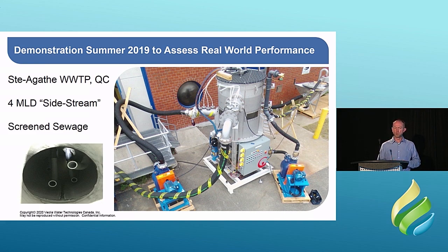Those are the sample tubes. And the bottom left photograph there is what those tubes are connected to. So those bendy pipes are picking up sample from various locations in that influent pipe. The whole idea being to get that representative sample. Don't take it from one point, take it from multiple points. Same kind of thing happening on the effluent manifold that you see kind of pointing towards us in the photograph.